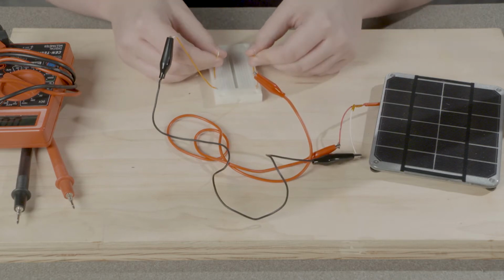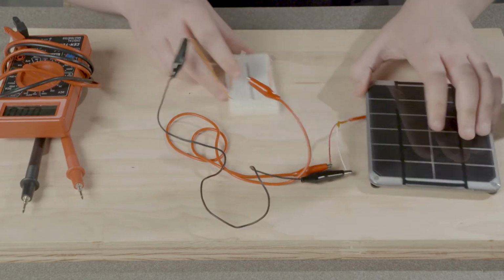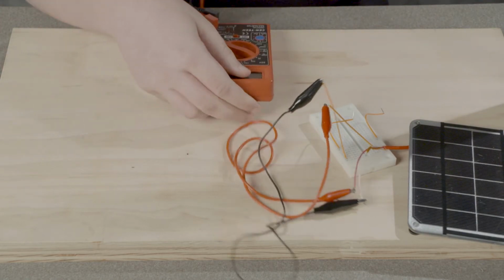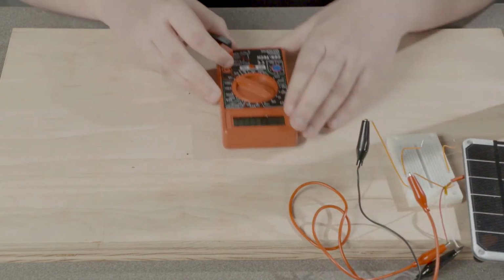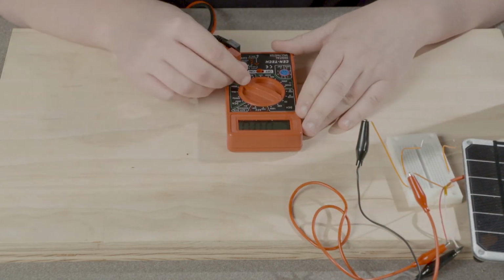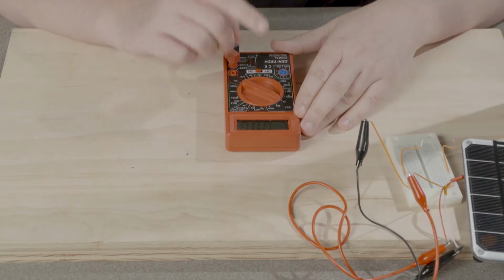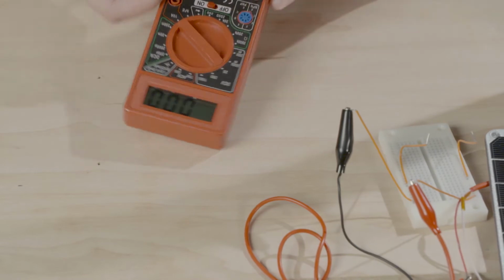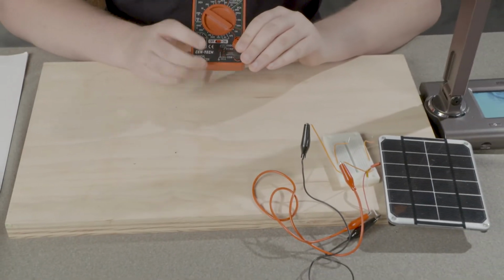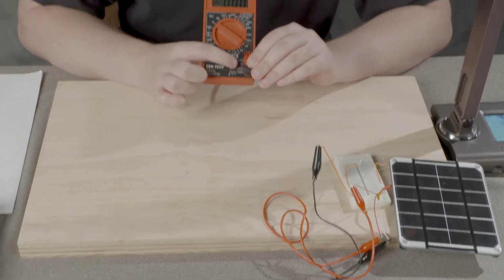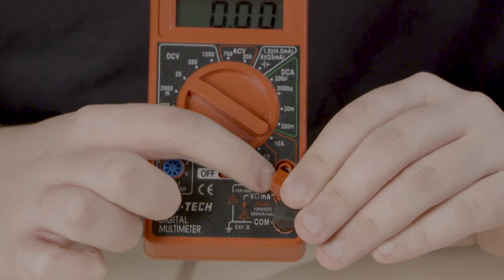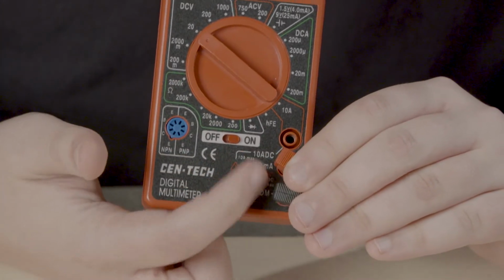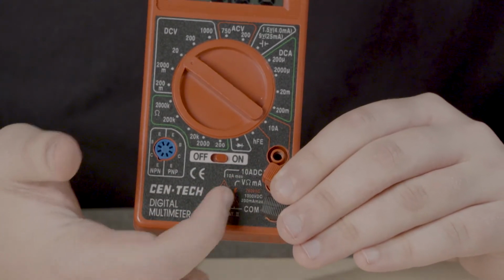So lift these up. And let's push this aside so I can show you how to use a multimeter. Okay. So when finding voltage, we're going to put it in parallel. We're going to be using a resistor, but I'm just showing you how to do it right now. The black should be in COM. And for this, we're only going to be in this place. We're never going to do the 10 amps DC right here. If we use it, we might actually blow the multimeter. So keep it where just these ports.